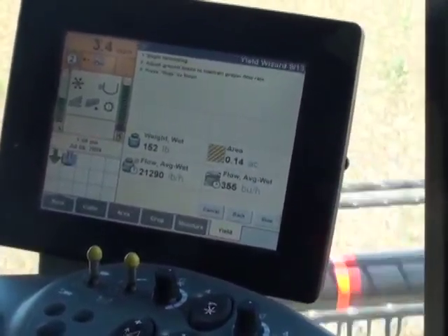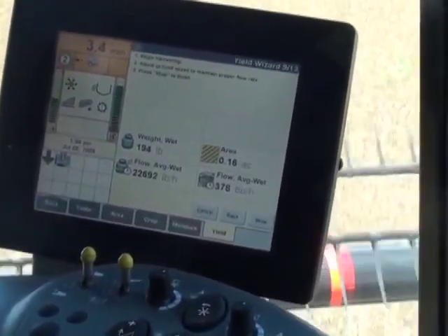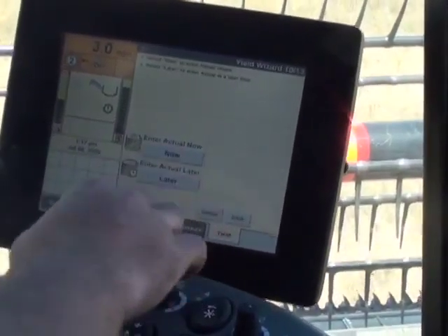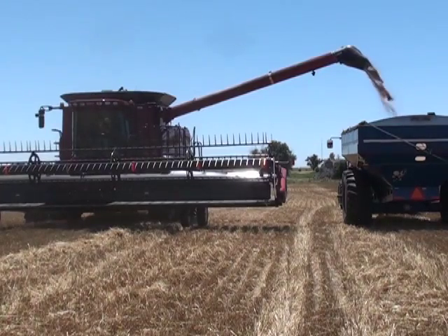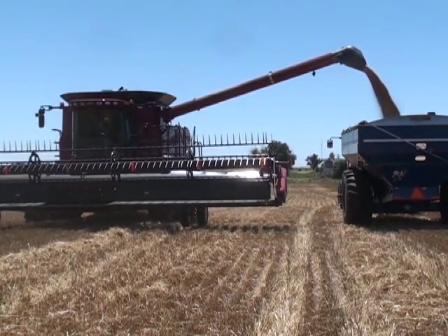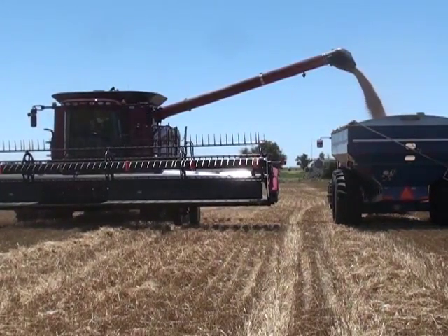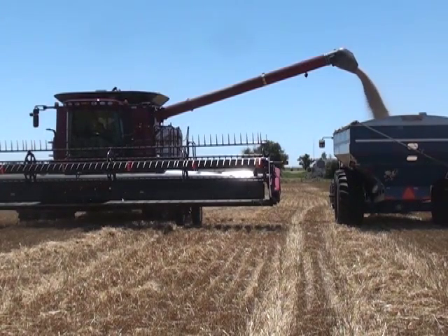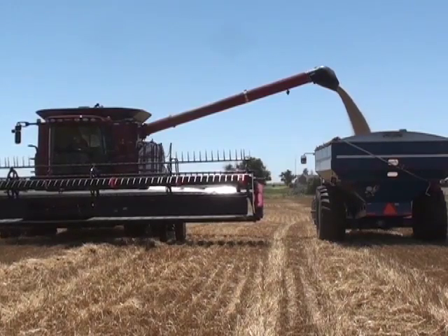When the desired crop volume has been harvested, stop the combine and allow crop inside the combine to finish processing. Then press the Stop button in the lower right corner of the display. Now obtain an actual weight for the harvested task. You may use a scale cart, elevator scale ticket, or other trusted source for actual weight. Ensure that the measuring device itself has been calibrated and proven to provide accurate results. The accuracy of your AFS yield calibration is dependent on the accuracy of the actual weight value you enter.